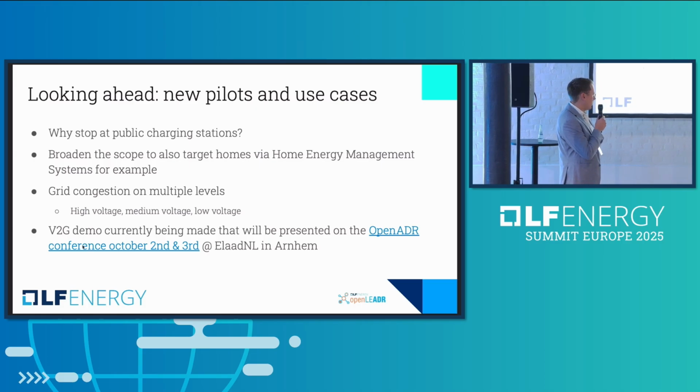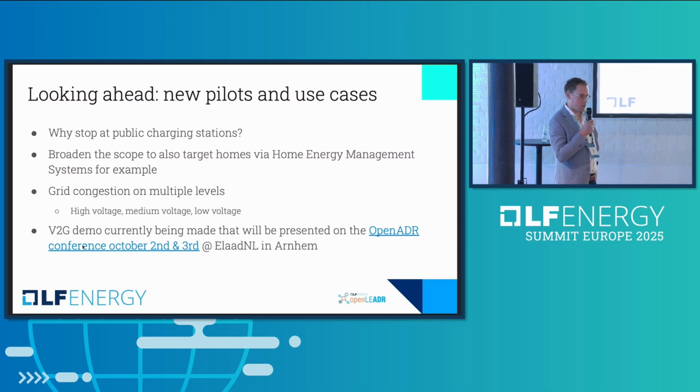And we're actually now building the first V2G OpenADR enabled demo where we can send a DSO signal to a CPO that will then trigger a charge point to do a V2G charging session. So we're able to utilize the car's power to balance the grid if needed. It's a very nice demo setup. It's not production anywhere near, but it's good to have this full chain set up somewhere and to show that it's actually technically possible. So we'll demo that at the ElaadNL premises in Arnhem at the beginning of October.